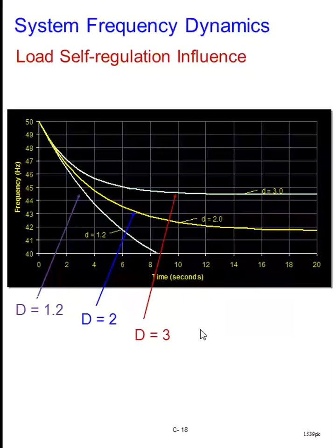If you just have lighting load, let's say out of 100% of the load, 80% are static loads, lighting loads, and the remaining 20% are motor loads, then in that case frequency regulation will be challenging.